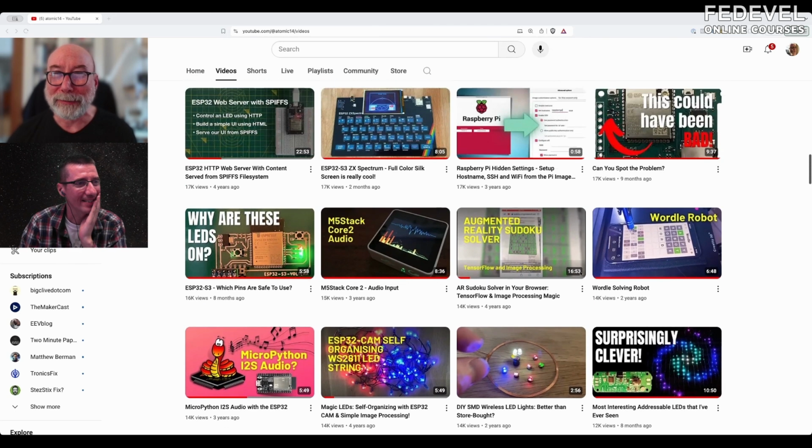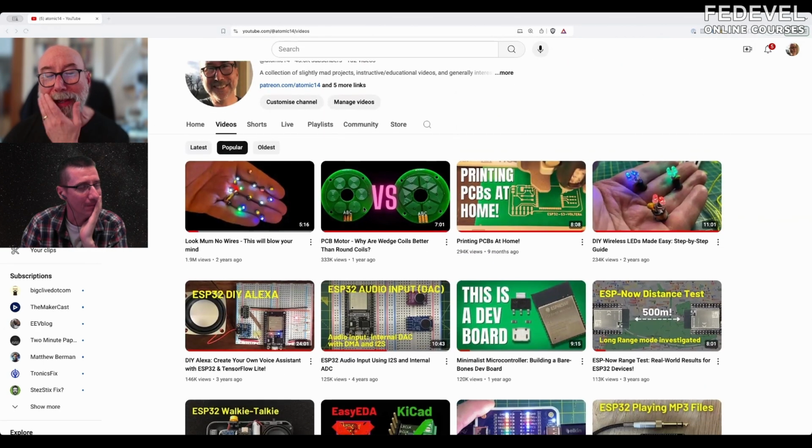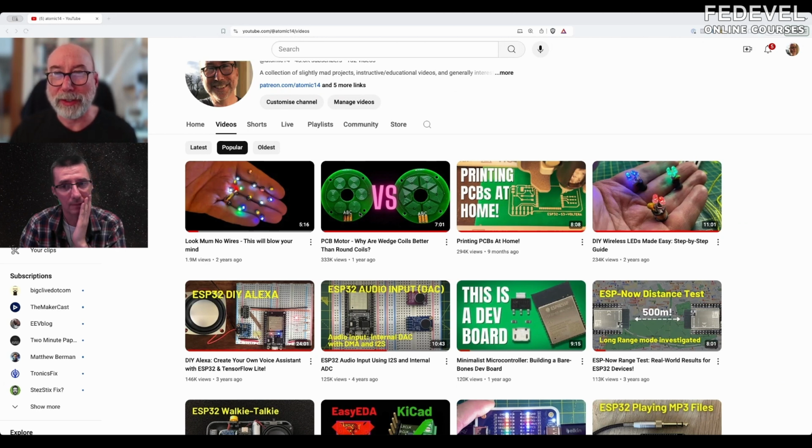Okay, so what is the second most popular project? Yeah, so the second one was the motor. I started playing around with coils on PCBs. A friend and I had seen one of those haptic knobs that use BLDC motors. So you have a kind of turn switch, but it has a motor built in, so you can have programmable detents on the switch.